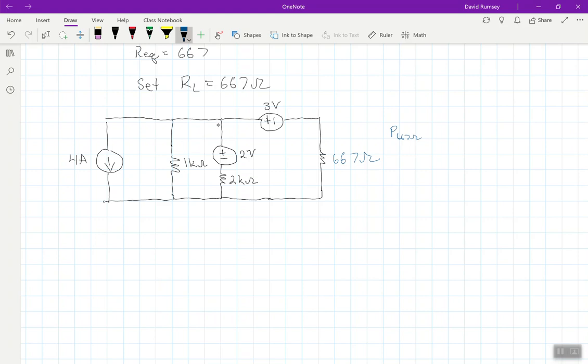and actually I've got some difficulty here because I've got a node here where it's like, oh wait, there's 2 volts here. So if I try to do this voltage minus this voltage, there's no resistance there. So that's actually going to make things a little bit more difficult for us. There's ways you could go about doing that, but they're a little bit more challenging. So what we're going to look at here instead is like, well, wait a minute, let's maybe try and do some loops.